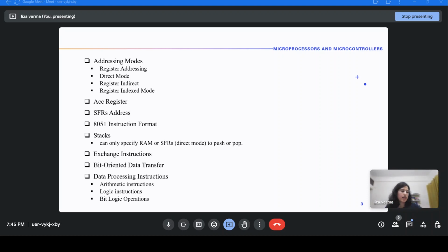So I think you can relate this to half adder and full adder, right? ADDC is like a full adder, ADD is like a half adder. ADDC will include the carry if a carry was generated in the previous addition operation, right? So for addition, we have this distinction.